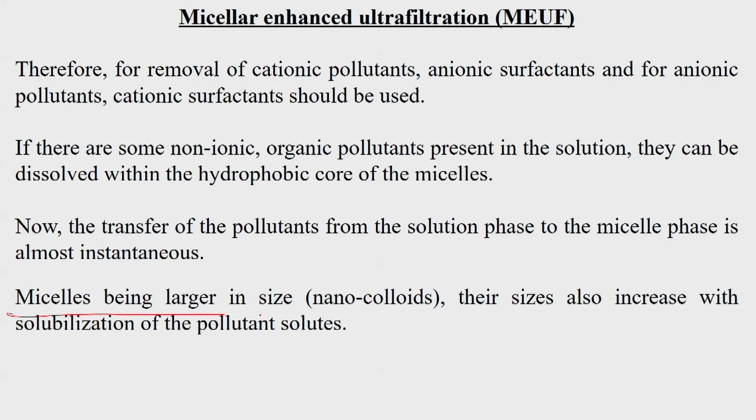Micelles, being larger in size like these nanocolloids, increase in size with the solubilization of the pollutants. Whenever the pollutants are attached at the top surface due to the electrostatic force of attraction, the size of the micelle will go on increasing. At the same time, if the solutes are solubilized inside the core of the micelles, the size of the micelle also increases, and one time will be reached when it will exceed its capacity limit.